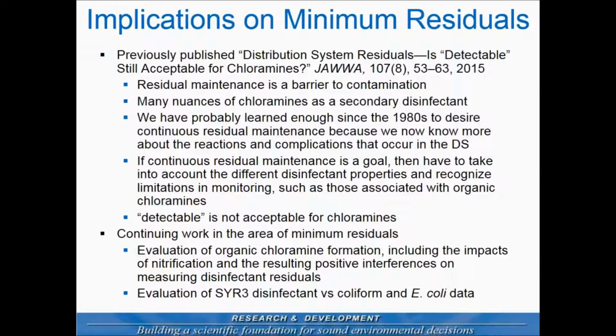And so if that is a goal, then we have to take into account the different disinfectant properties and recognize limitations in monitoring, such as those associated with organic chloramines. And so we felt that detectable is not acceptable for chloramines. Since that point, we're continuing our work in the area of minimum residuals. We're doing some research on evaluating organic chloramine formation, including the impacts of nitrification and the resulting positive interferences on measuring disinfectant residuals. And we've worked with some of our colleagues in the Office of Water on some evaluation of Six-Year Review 3 disinfectant versus microbial data.